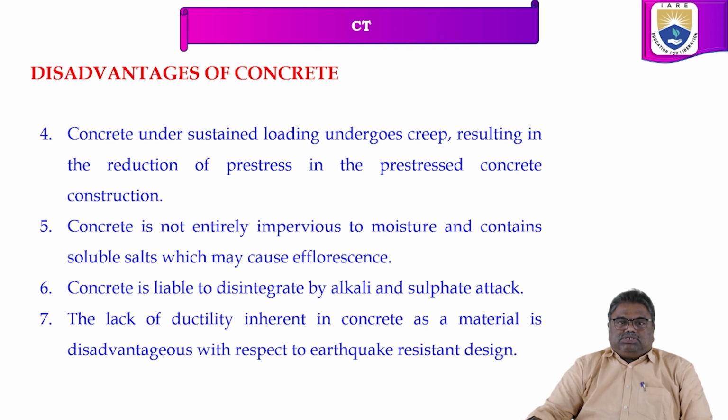The fifth one: concrete is not entirely impervious. Concrete is not entirely impervious to moisture, and it contains soluble salts which may cause efflorescence. It is pervious only, right? So it will take the moisture and soluble salts, which cause efflorescence in the concrete. The sixth one: concrete is liable to disintegrate by alkali and sulfate attack.